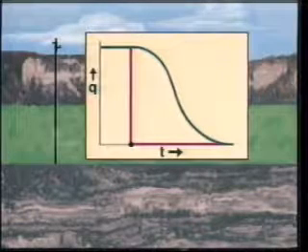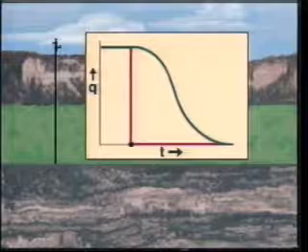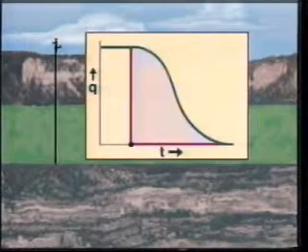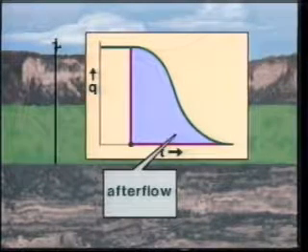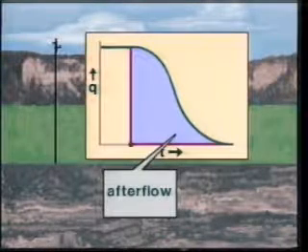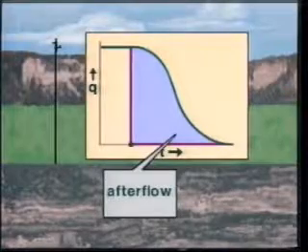At the surface, the flow rate drops sharply to zero. The wellbore flow rate, though, drops more gradually to zero. The difference is caused by another wellbore storage effect, afterflow, caused by fluid compression in the wellbore. Note also that wellbore storage takes place early in the life of a well test.